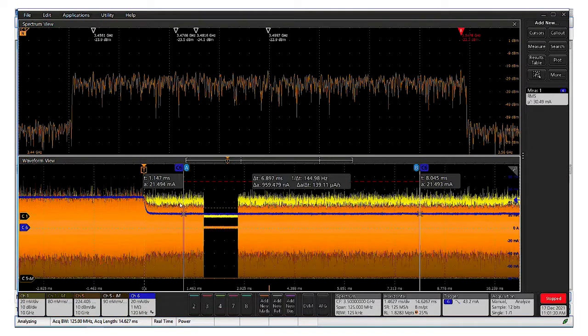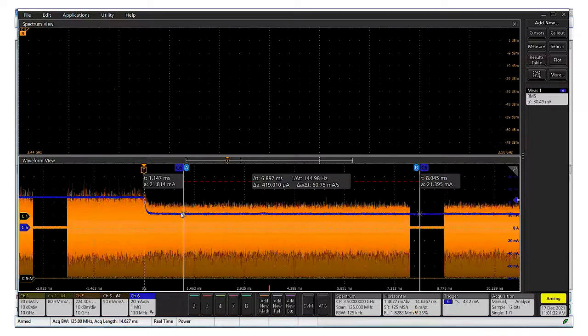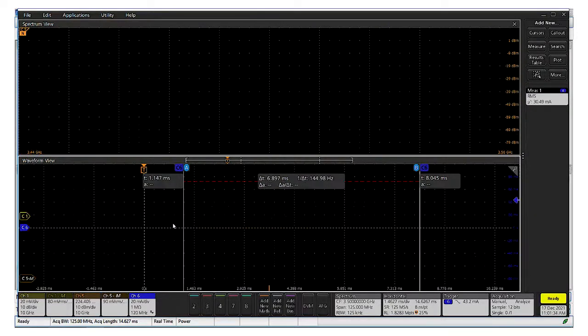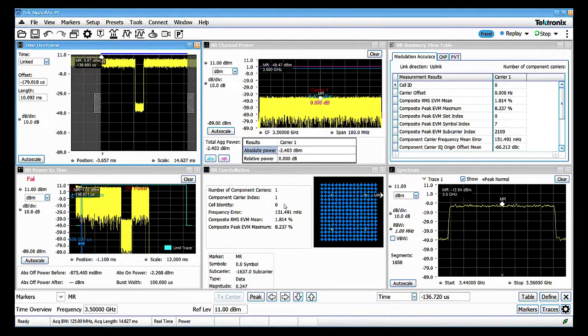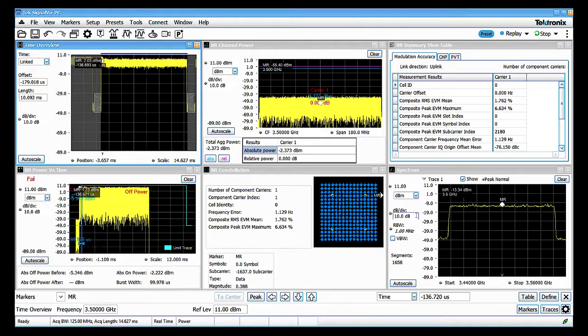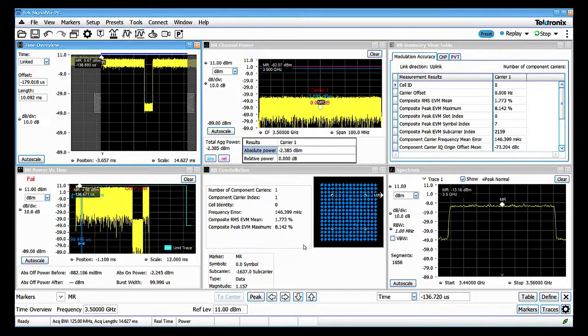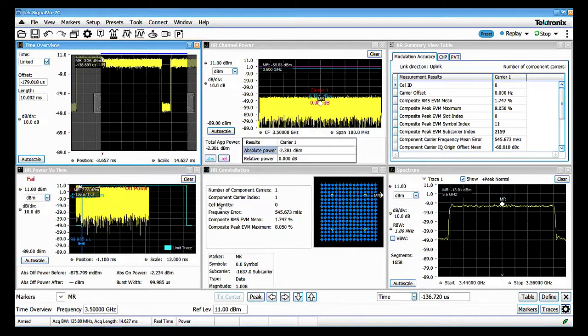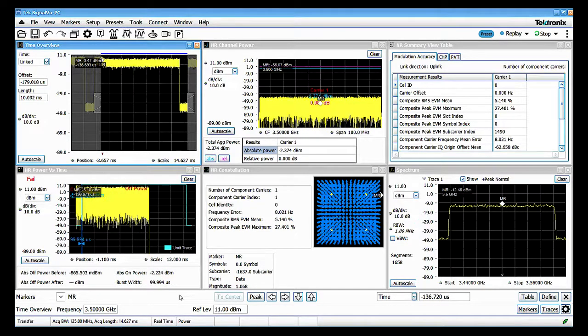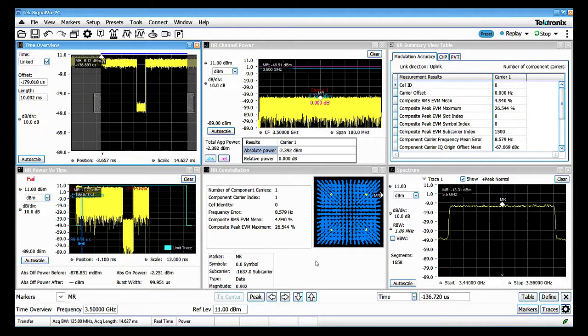We're correlating now the cause of our RF drop with the oscilloscope. And when we go to SignalVu, we can now catch the moment when the current starts dropping out. Here we see that the current is perfectly correlated with the RF drop on the scope screen. Sure enough, now that we've triggered on the dropout in current, we no longer have a flickering constellation, an EVM display, and we have a much better look at our real problem. And you can see that our EVM is always high because we've triggered on the moment of failure.